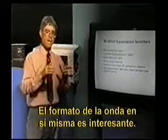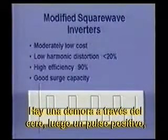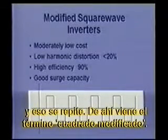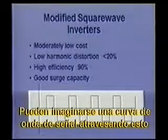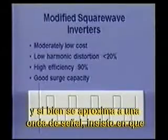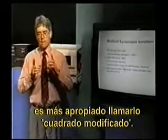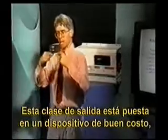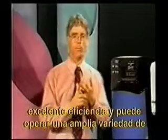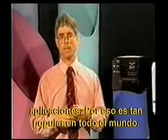The waveform shape itself is kind of an interesting thing to look at. There's a delay through zero, then a positive pulse, then a delay through zero, and then a negative pulse, and that repeats. That's where I get the term modified square. You can sort of imagine a sine wave curve going through this, and it approximates the sine wave. But I think it's more appropriate to call it a modified square. This type of output is designed into a device that's of good cost, excellent efficiency, and can operate a wide variety of applications. So we find it being the inverter of choice in many cases around the world.